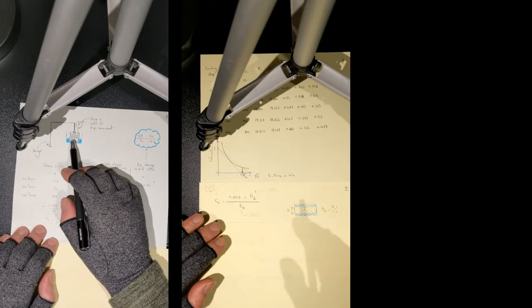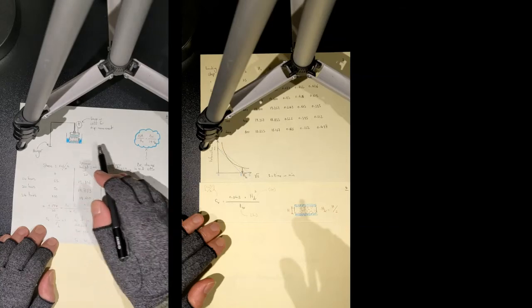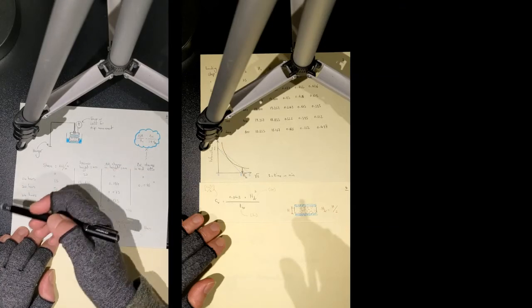Now, the water content, which is the saturated water content, is effectively known. You can have two identical oedometer samples, keep one for the testing, and put one in the oven to measure its water content, and that water content is equal to w sat. So if you have your w sat, S sub r and Gs, you can determine your e naught, or initial void ratio. If you go this way, then your e naught will be equal to the water content, which you can measure in the laboratory, multiplied by Gs. So either this way or this way, you can get your void ratio. The choice of approach is up to you. And that is your initial void ratio.